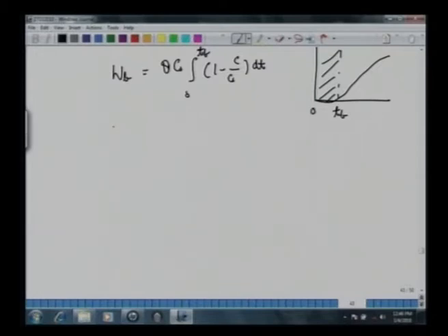How much amount is absorbed till WS, which we have defined like TS here, so that this area is the same as this area, is the stoichiometric or ideal front. This would be Q into C0, integral 0 to TS, of 1 minus C over C0 dt. So that would be the area till this TS above the curve.